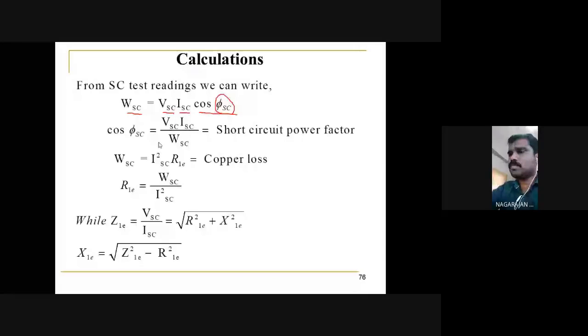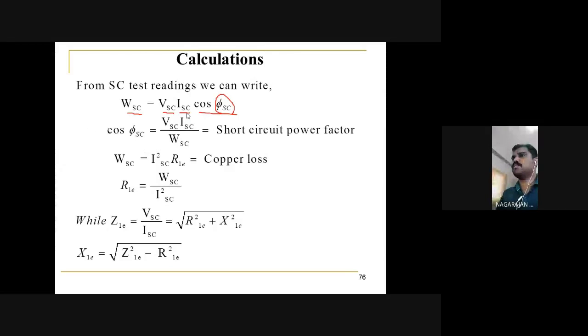So WSC in terms of voltage and current is given as VSC ISC cos phi SC. From this we are measuring the short circuit power factor.